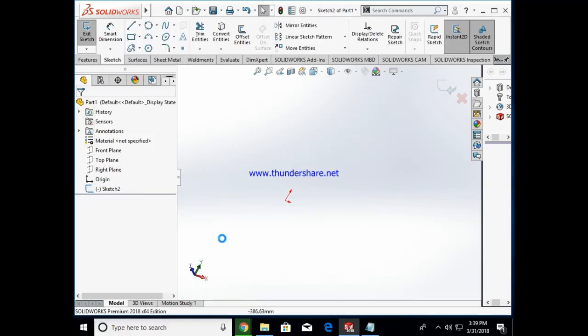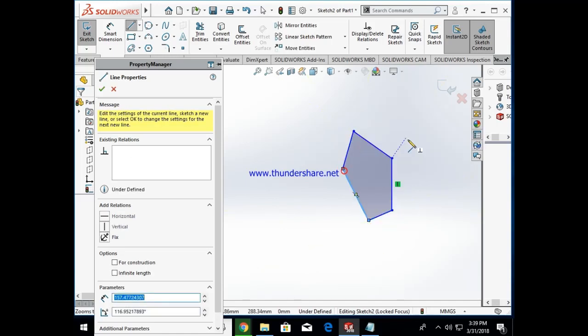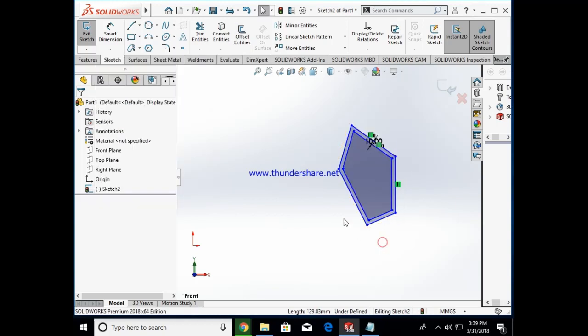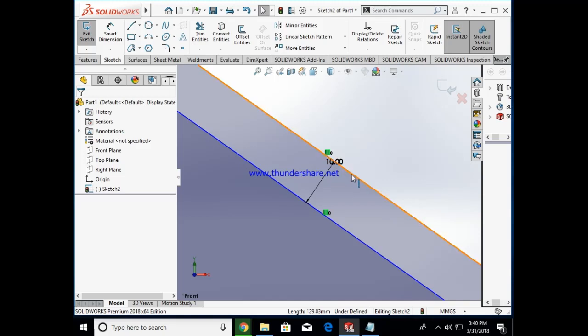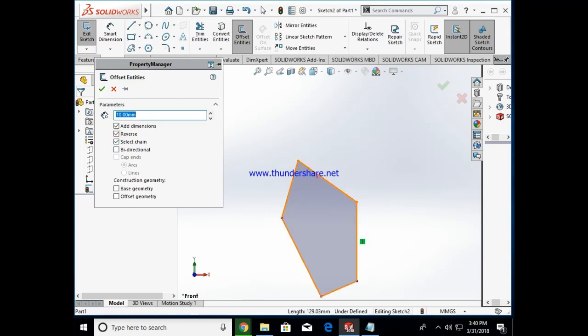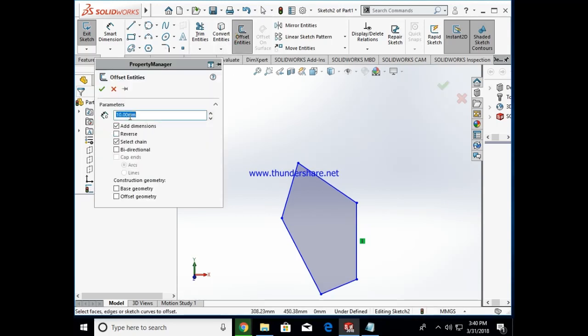Now I'm creating a closed line shape. I'm using the offset command. Offset is nothing but the same object at some distance. In offset you have a reverse option, which will go in the reverse direction. So you need to select that value. 10 is very small, I think, so you can give some small value such that I'm getting the object value 2. So it will give a value of 2. You can see there 2 selected; with reverse, it goes in the reverse direction.